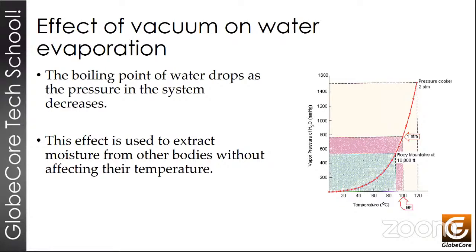It's well known that water evaporates at 100 C, but this is just half of the story, because to describe this property completely, we should say that water evaporates at 100 degrees centigrade at 1 atmosphere of pressure. The influence of pressure is very important in the boiling process, because when pressure is higher, so is the boiling point. These two are directly proportional. When the pressure decreases, so does the boiling temperature. This is important because we want to boil moisture out of the oil without the need to heat it to temperatures that can damage the oil.